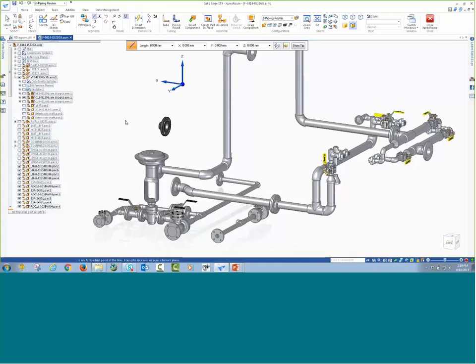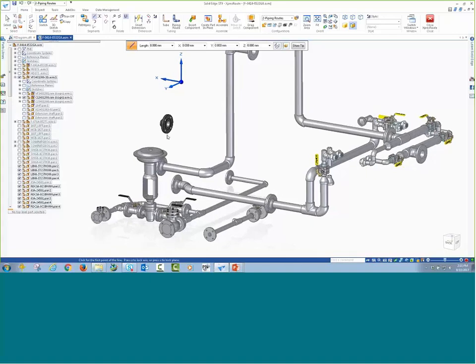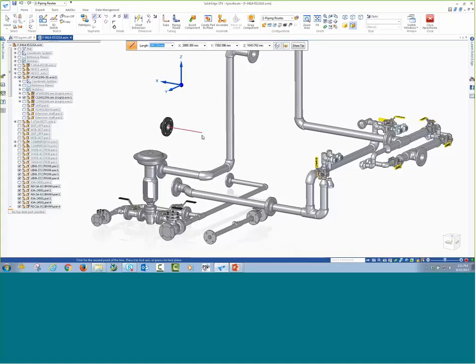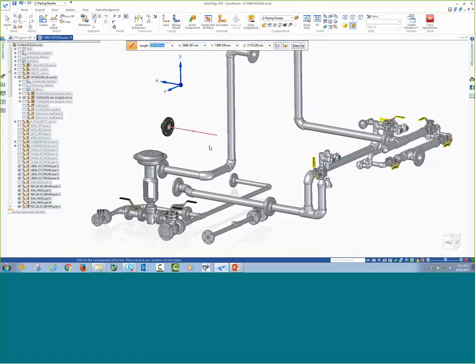And Orient Express allows us to just tag specific components. In this case, I want to start a route that's coming right from this flange. And you'll notice that it automatically comes out straight out of the component that we've selected. You'll notice at the top of the screen, if I want to key in a specific value, I can do that here. Let's say I want to come out 500 millimeters exactly. And then I can specify which direction that comes out in this case.